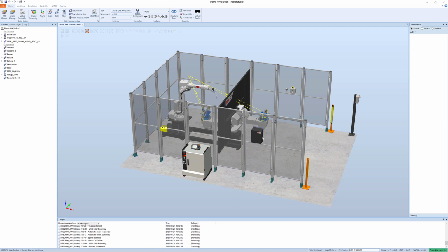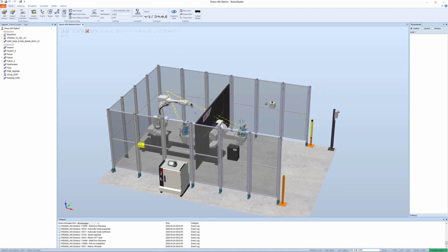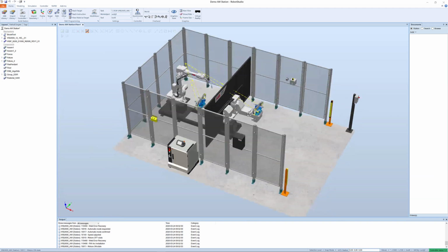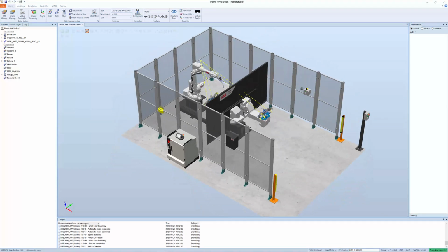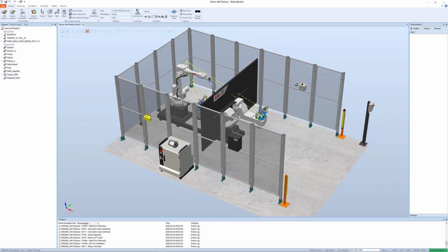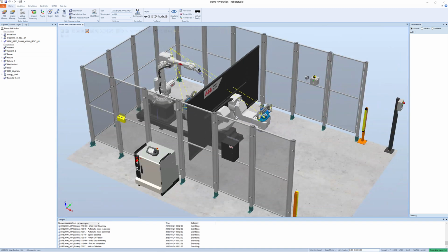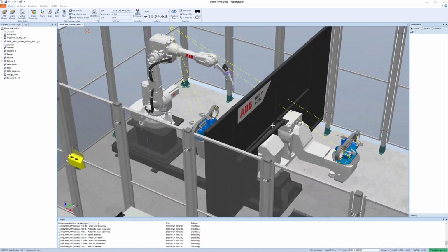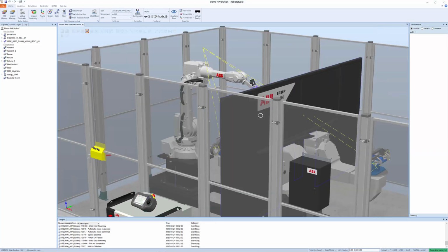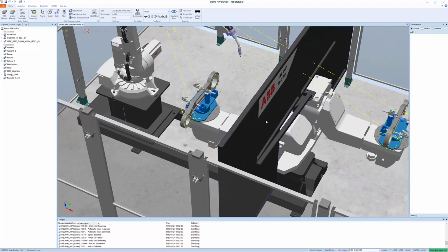To move around as a user, if I hold down the Control key and the left mouse button, I can pan around like this. That's fine. If I use Control-Shift, I can rotate this one. And I can zoom with the middle wheel button, so to say. I just turn the middle wheel, and I can zoom in. So basically, Control-left is pan, Control-Shift is rotate, and zoom in and out using the wheel.